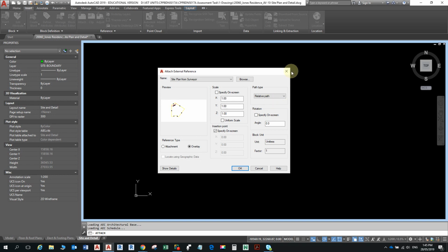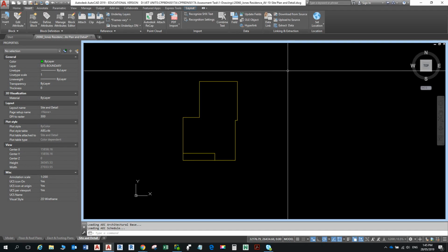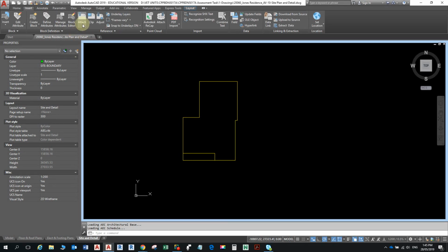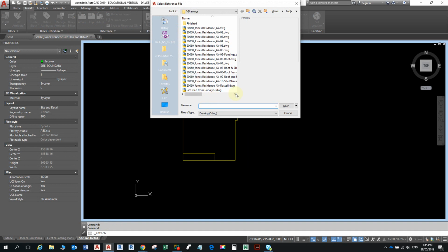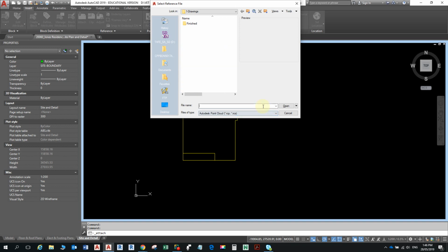Okay, so everyone please listen, because this is important. If you're wanting to bring any images in, anything, images as well, PDF, anything, into AutoCAD, I'll show you. By the way, speaking of PDF, there's two ways of bringing it in. One is through attach, which is here, and then you can see you can bring DGN, which is MicroStation files. You can bring DWF. You can bring in point clouds, which is a ReCap version of point clouds, which basically surveyors will come in with a scanner and scan this building, and you can bring it in as that. What else? Yeah, drawing files, of course.